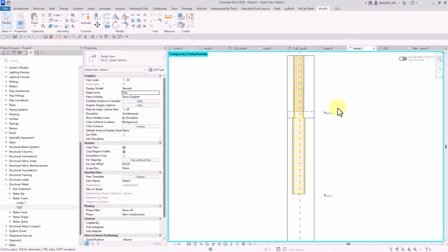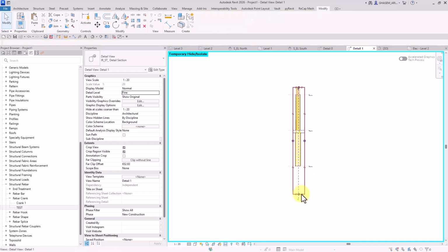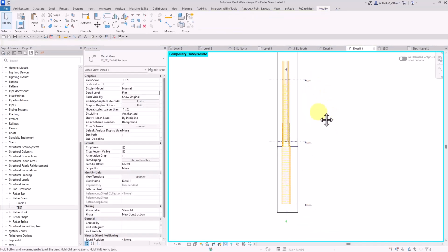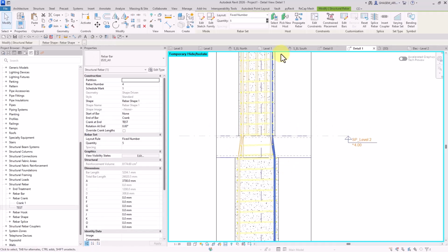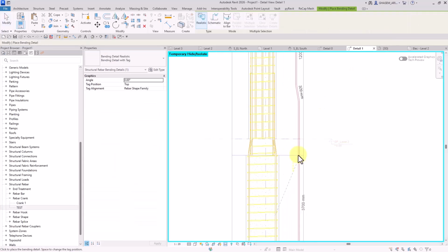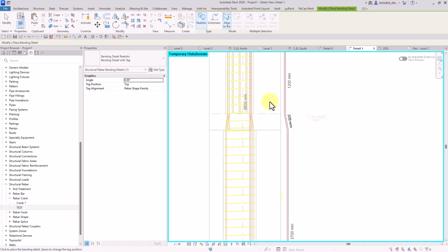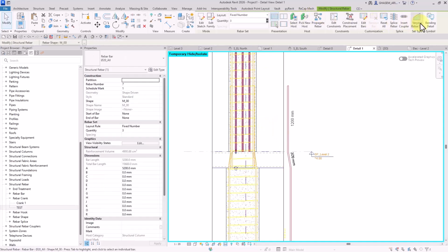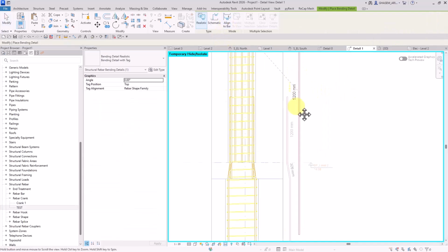Alright guys, we have our rebars, we have our cranks, and now we can start using these wherever we want based on our needs. As an example, I'm gonna select this, and up here from bending, I'm gonna select align, select this top one, cancel, here, bending again, where was it?